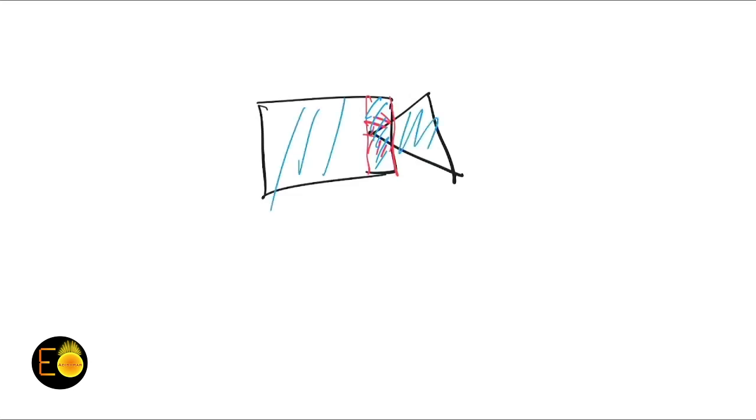So if we do uniform meshing, and you need a very accurate calculation, then in order to get denser meshing over there, by default we also have to increase the meshing everywhere else, because we are choosing uniform meshing.